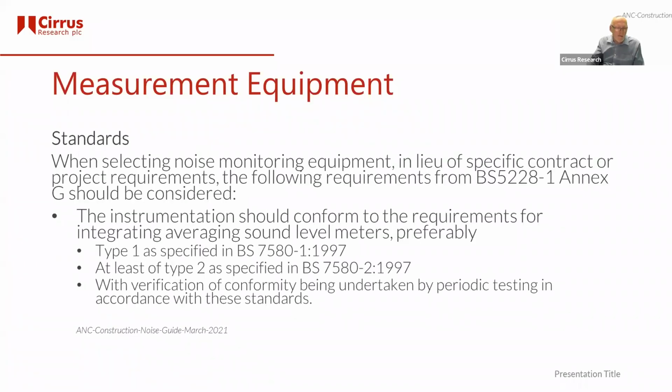I've taken this from the Acoustics and Noise Consultants Construction Noise Guide, March 2021, which specifies the standards, and that's taken from BS 5228, which I think was last updated in 2014. It specifies the instrumentation, i.e. the measurement equipment that you're going to use, and in their eyes it should be type 1, but in any case at least type 2.